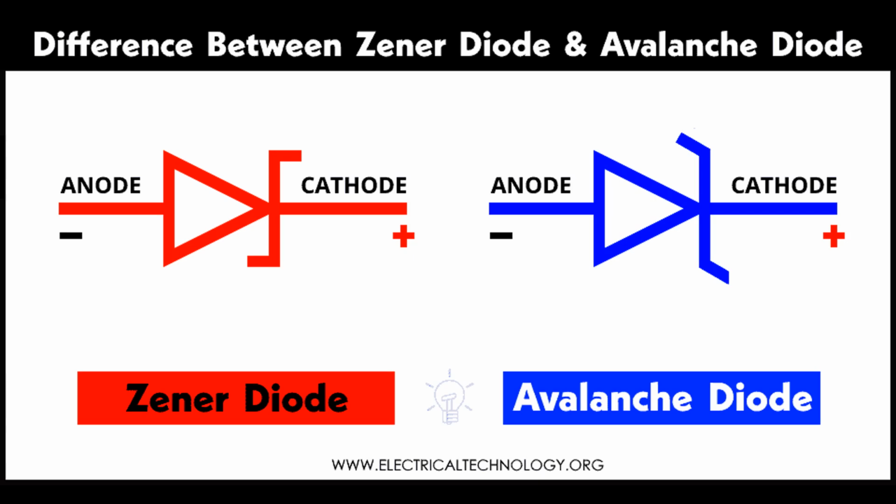Zener voltage regulator. Components: Zener diode, VZ equals 5.6 V. Series resistor, R. Input voltage, VIN equals 12 V. Load resistor, RL. Circuit description: The series resistor, R, limits the current through the Zener diode. The Zener diode maintains a constant 5.6 V across the load resistor.